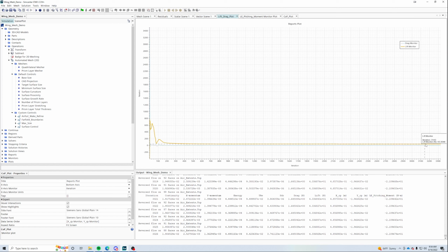We have a change of like 1/10 of a Newton out of 40 for lift, and basically nothing for drag. So there's some very, very tiny changes. This is pretty insensitive to the change in the mesh in this case. Other cases might not be so insensitive. And actually, that's one of the tests to determine if your simulation is meshed finely enough.